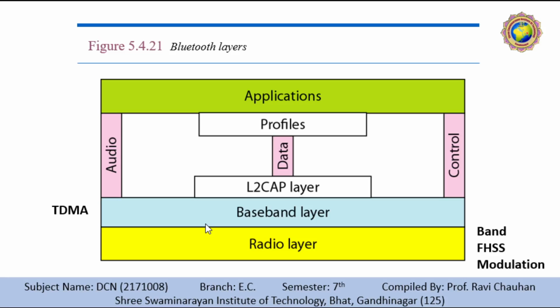This means that during the time that one frequency is used, a primary sends a frame to the secondary, or a secondary sends a frame to the primary. Note that the communication is only between the primary and the secondary. Secondaries cannot communicate directly with one another. A primary is required for the transmission of data from one secondary to another secondary.